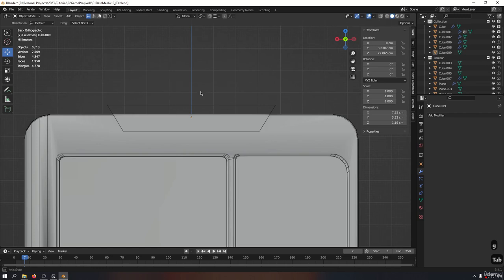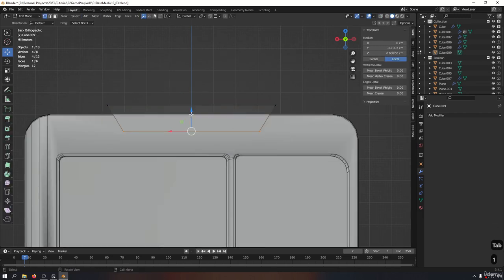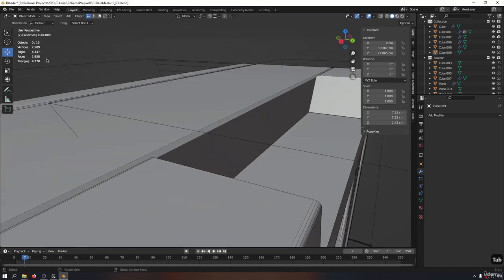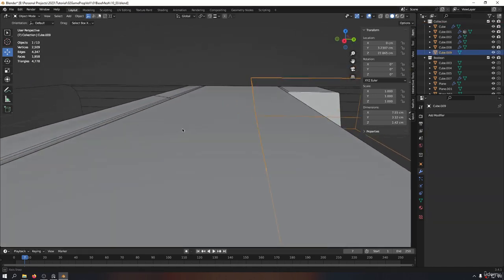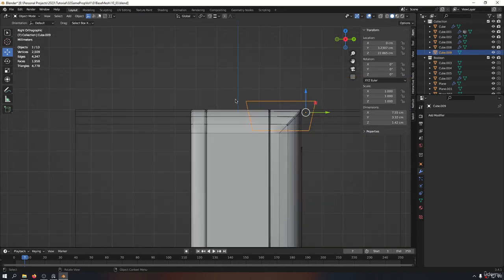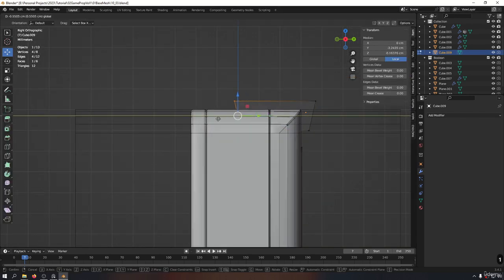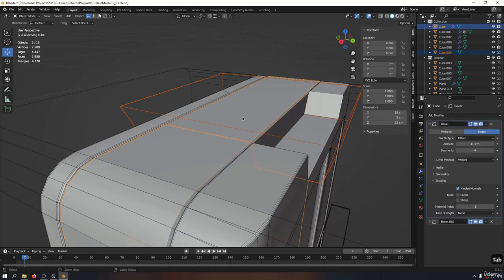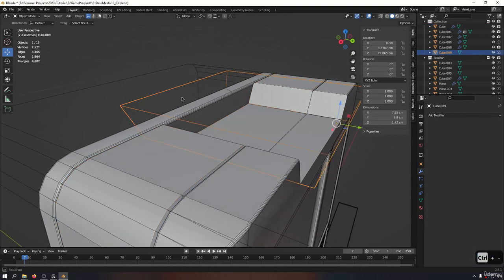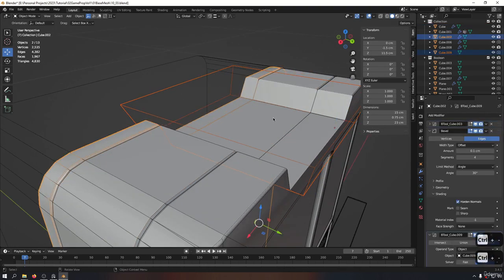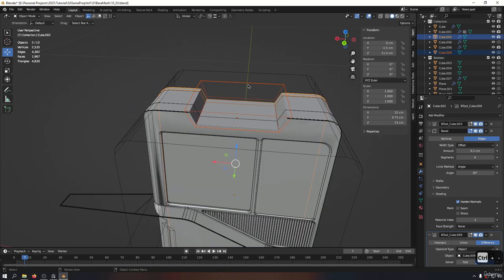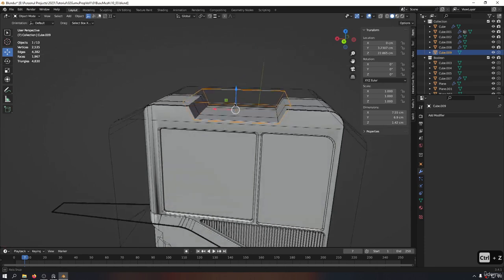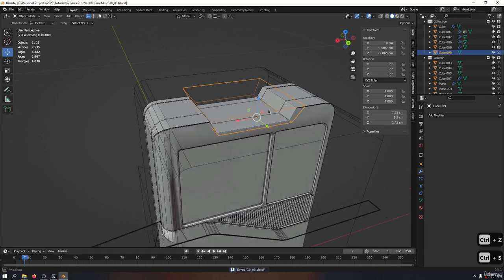Okay. Now looks like we could go and try to cut this one even further. And you see now it's not cutting through all the way to the end. That is because we have not yet aligned this Boolean to those pieces. So again, let me take this piece and drag it back. And then I'm going to take it and this one, Control minus. And again, take this and the next piece and Control minus. Okay, now you see this piece we have. Now it's live and it's doing the changes on these pieces, which is perfect.